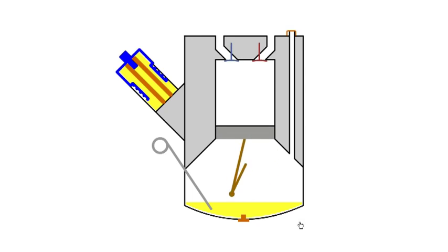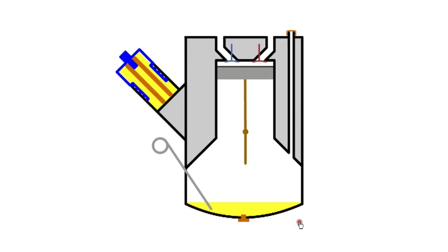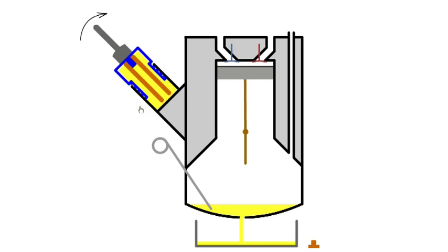Before changing oil, we run the engine for a short period to warm the oil. A container is placed under the sump, the filler cap is removed, and we open the drain plug. While the oil is draining, the oil filter is replaced. This is a cartridge filter which is contained in a removable housing.